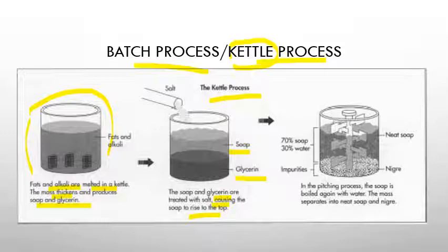If a small quantity of the fat did not saponify, a strong alkaline solution is added in the kettle, so that saponification takes place again, and then again the salt is added. So the third step involves this: if some fat remains unsaponified, we add caustic soda solution again, and again add the salt for complete saponification. So that step is strong change.